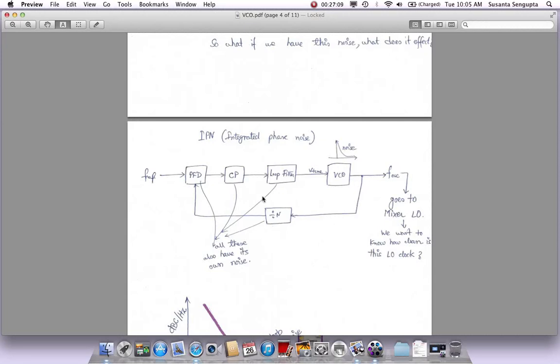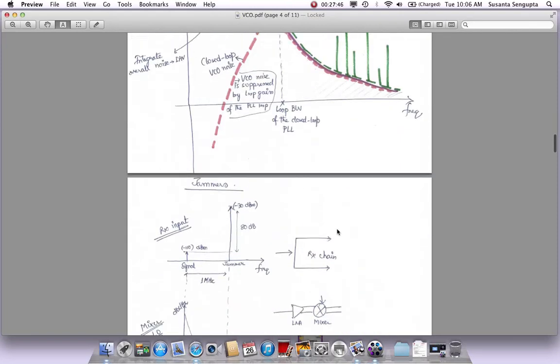This loop has less pressure now, and you have already brought it closer to what the output frequency should be. Now you're telling the loop, hey, go ahead and finish the rest 10% of the job and lock me exactly to the final frequency you want. Then the loop will go around and give you the right V-tune to give you the final one. So that's how we do it. We don't put complete pressure on these blocks. We first calibrate it, bring it close. While this loop is broken, these blocks are kept off, and then these blocks are turned on and told, settle down to the final V-tune value, so I get the final frequency that I'm looking for.